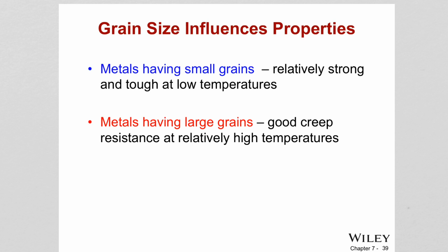Grain size has a direct effect on the properties. If you have small grains, you have a material that is strong and tough at room temperatures. If you have large grains, this can have good creep resistance at relatively high temperatures.